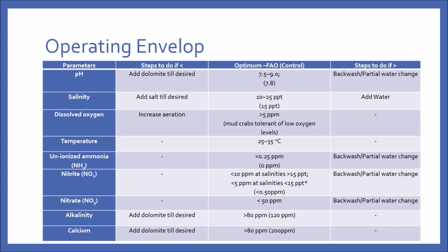This is known as blood toxicity. Whereas in a saltwater condition, greater than 15 ppt, the lethal concentration for nitrite increases because chloride ions will compete for the space for nitrite, rendering the organisms more resistant to nitrite. In the event that you have high nitrites, do perform some sort of water change to reduce the concentration levels.